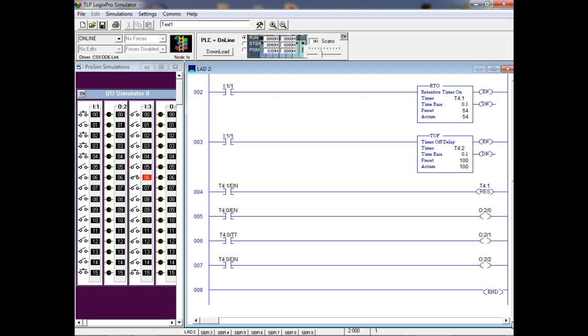And we're only looking at one timer. So right now, that timer up there is enabled, and it's what? Timed. It met its value, right? You understand. But the rung is still what? It's still true or enabled, right? You understand the difference between those two bits? Yes or no? And they are bits because they're what? One binary digit, right? Everybody okay? Any questions?